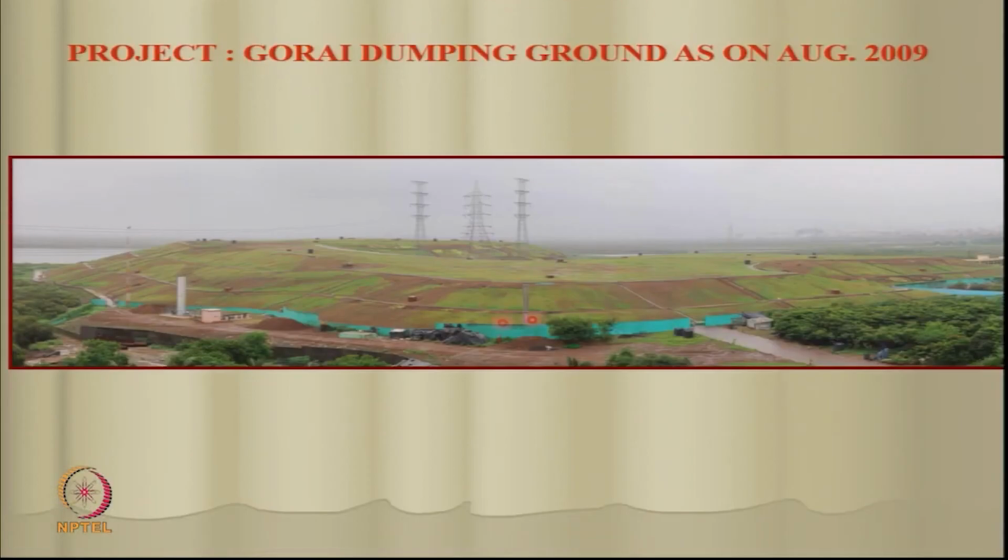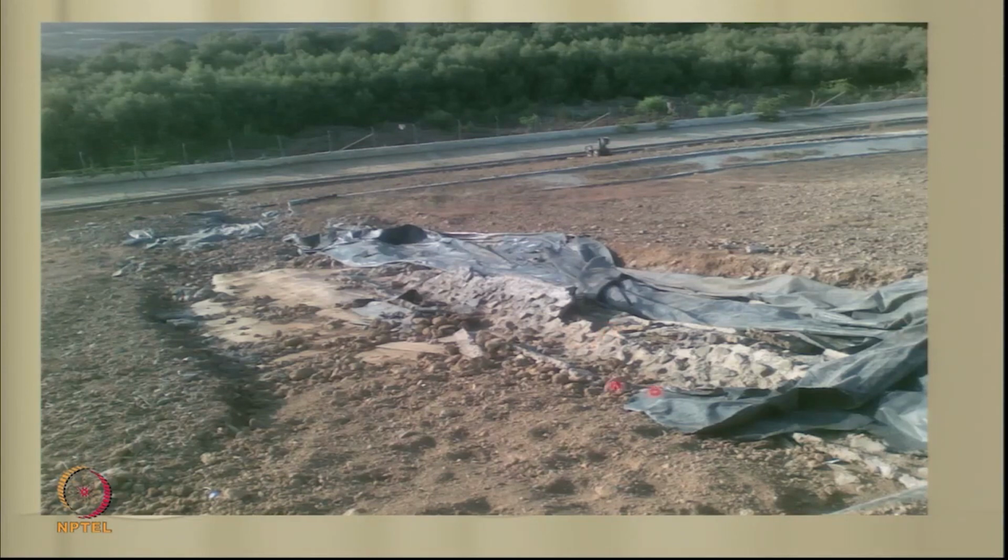And eventually, of course, this is what it looked like. But the story is that this can also happen. This is the drain which carries the water downwards. This is the erosion which has taken place. When you make these layers very thin, then the geomembrane can get exposed because you can slide along this. So unless you have a good vegetative cover which is formed and sustained, if you make the things very thin, they are highly prone to erosion. If it was thicker, then at least you would have an erosion gully, but you would not have reached the level of your geomembrane.